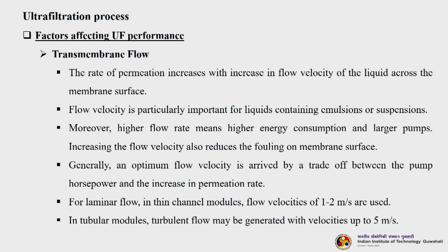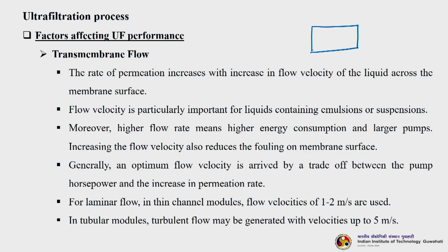The first one is the transmembrane flow. The rate of permeation increases with increase in flow velocity of the liquid across the membrane surface. We have discussed this earlier also, but I will try to make you understand again. Let us say this is our feed coming, and we are getting here the retentate and we get our permeate, the usual cross flow system. Now, as the separation progresses with time, the solute starts getting deposited on the surface of the membrane.